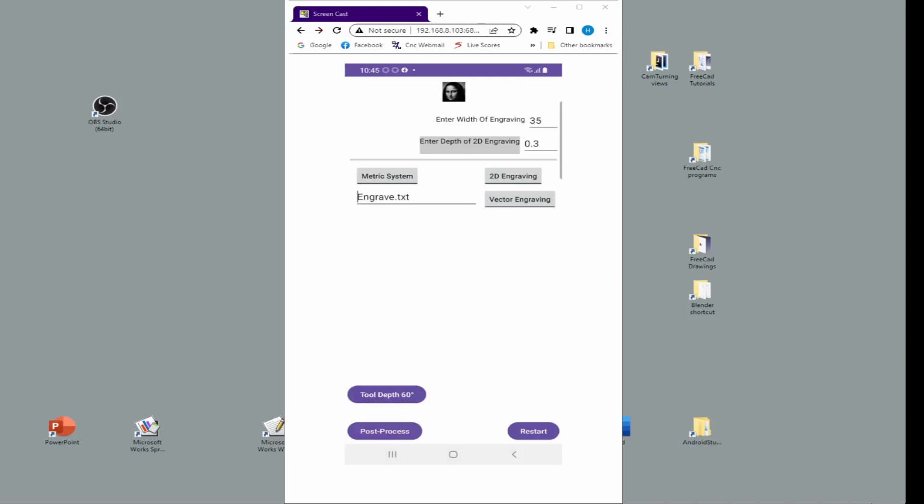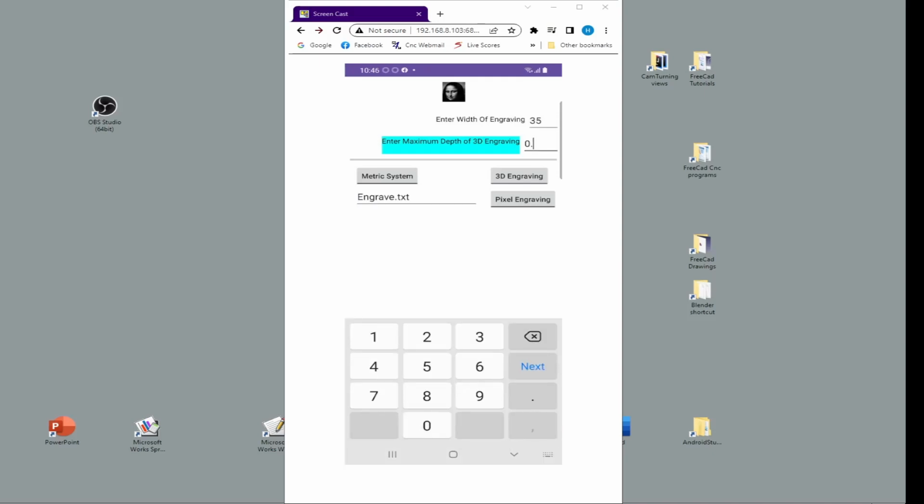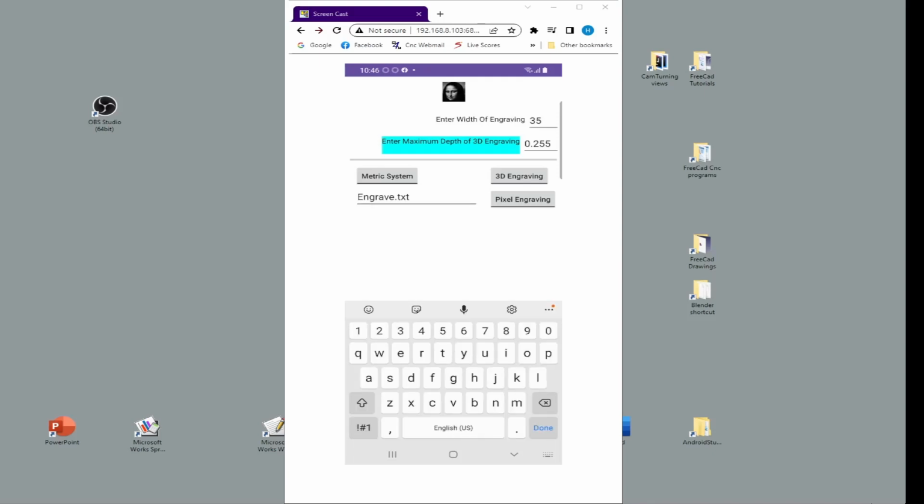In vector engraving, the cutter will stay down until it sees a white pixel and then lift up to safe distance. In pixel engraving, the cutter will lift to safe distance after every pixel. Use, as a rule, pixel engraving when you engrave photo images because photos are made of pixels. The left engraving on the London Tower top is done in pixel engraving and the right side in vector engraving. So, decide for yourself.